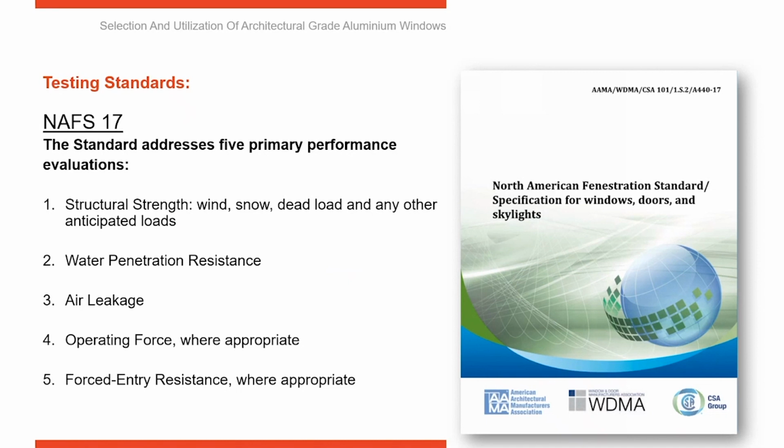That is structural strength, which is wind load, snow load, forces applied against an elevation 24 hours a day, 7 days a week. Water penetration resistance, air leakage, operating force, and I say where appropriate because obviously in a fixed window, you're not going to have operating force. Same with forced entry resistance. That's only in operable units. So NAFS 17 looks at these 5 evaluations.